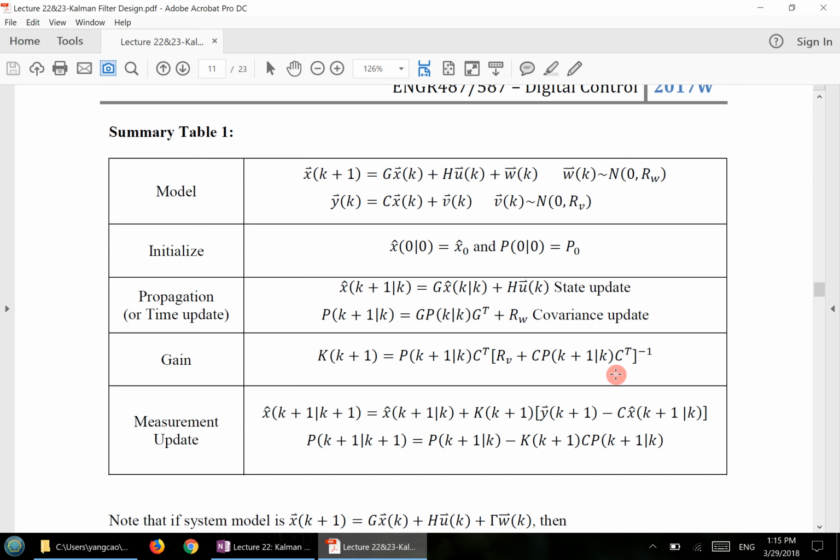Here, right? This is the results you get here. So your gain K will be this one, okay? And then there are different steps to implement this discrete-time Kalman filter. Technically, in terms of implementation, 1, 2, 3, 4, 5, so 5 lines of code basically, right? All you need is just 5 lines of code in order to implement this Kalman filter. Okay. So it's not too bad actually.